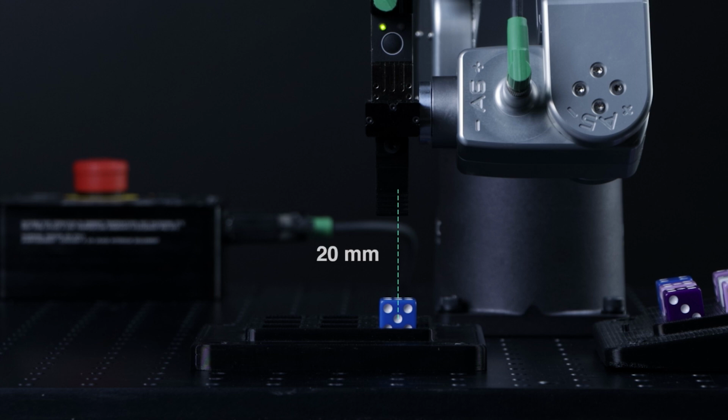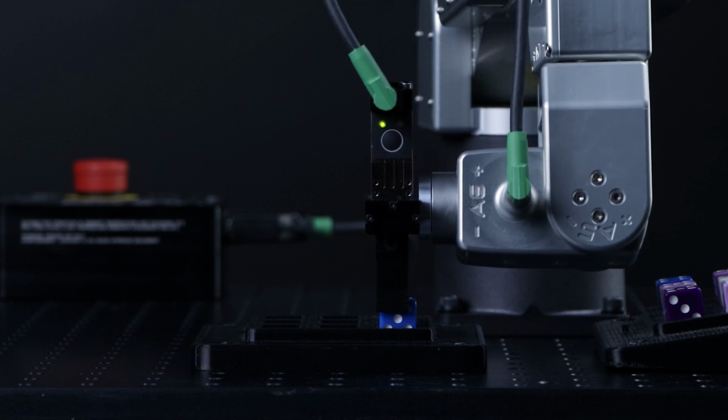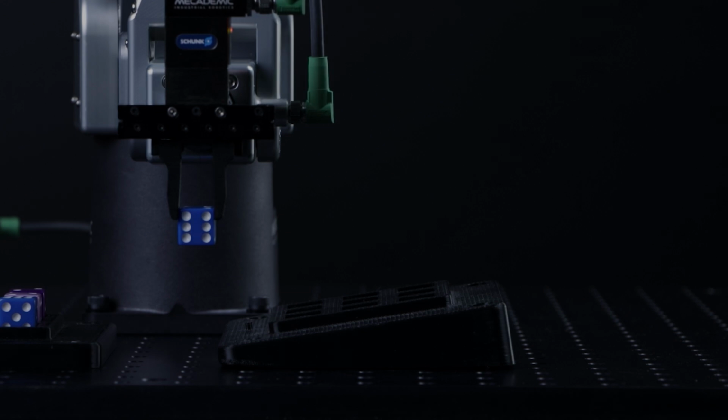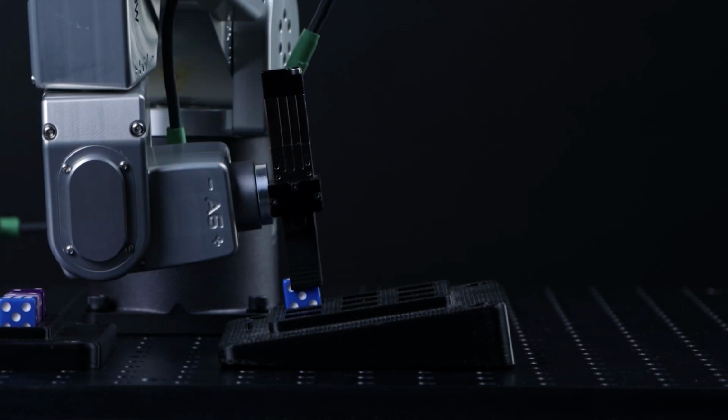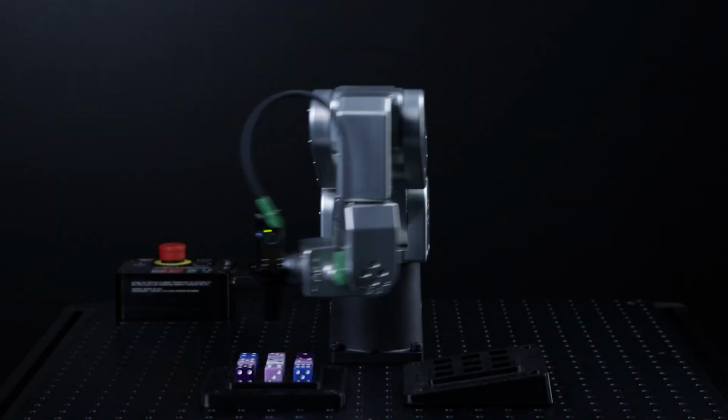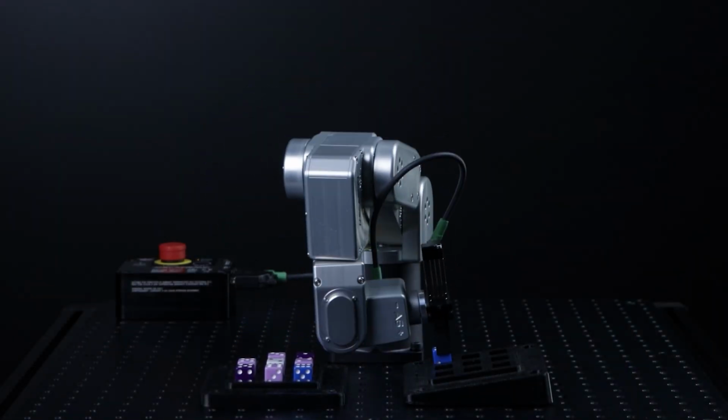We approach our position with a joint move at 20 millimeters along Z from our target, go down with a linear move, close our gripper, and then retract back along Z at 20 millimeters. A place would most likely be very similar, but would open the gripper, and the approach and retract positions would likely be interchanged. But we'll talk about the place sequence later.